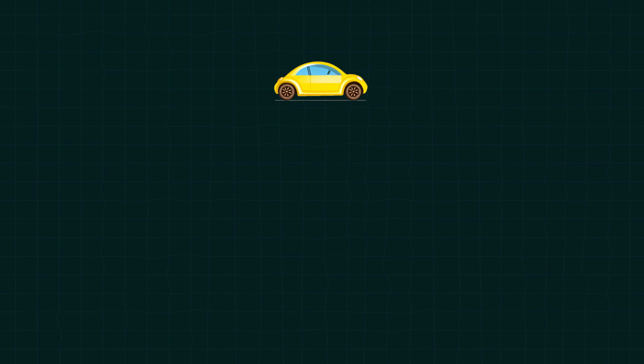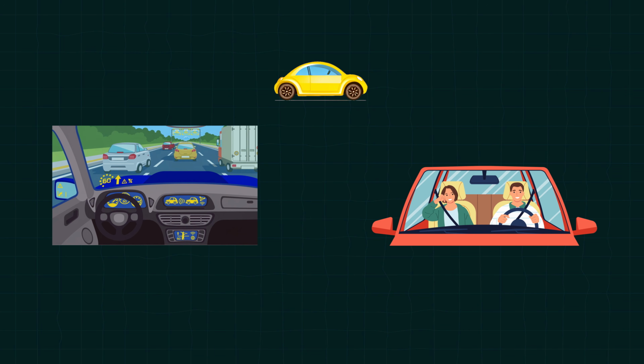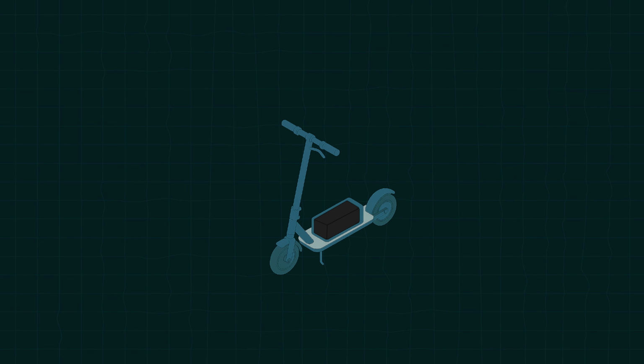You might think, I've only got a 24 volt or 48 volt battery pack. Do I really need a fancy AFE chip? The answer is yes. Even low voltage packs benefit big time from an AFE. It's like asking if a small car needs a dashboard or seat belts. Of course, it does. Just because the pack's voltage is lower doesn't mean it can slack off on safety and monitoring.